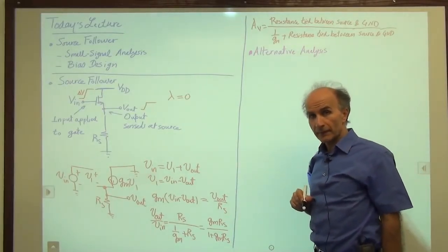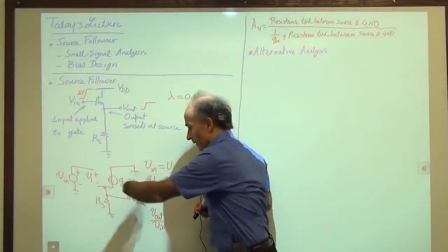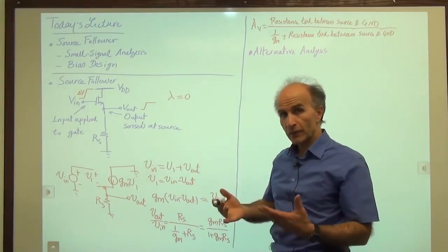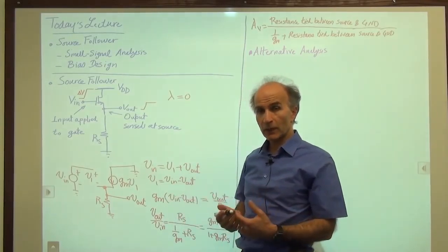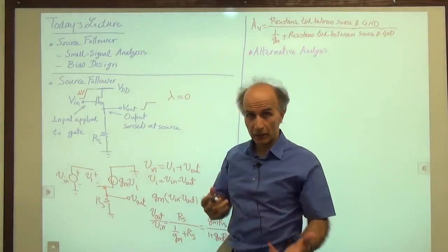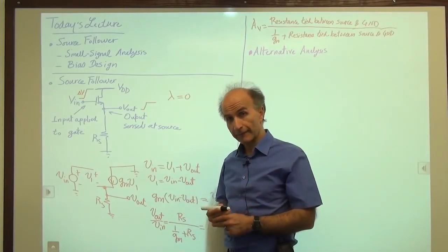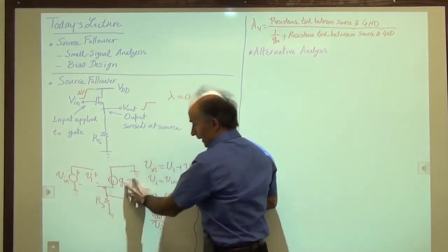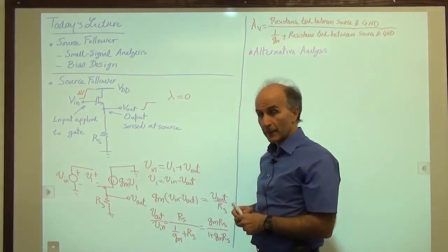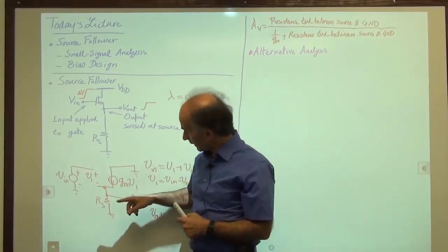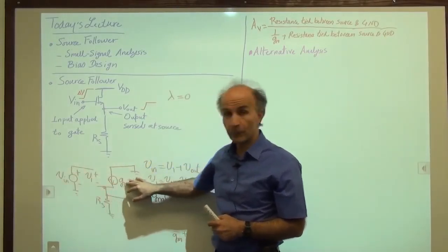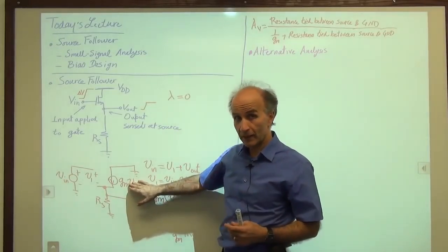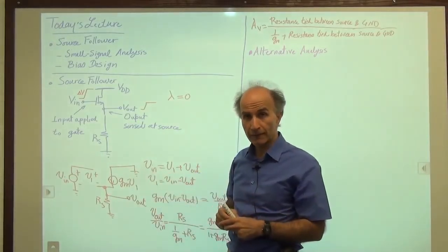All right, so let's do this. Rather than go through the small signal analysis and write all these equations, maybe we can use some of our knowledge from Circuits 101, namely Thevenin equivalent, Norton equivalent, that sort of thing, right? So maybe what I can do is this. I have the circuit, and I'm too lazy to write these equations. So I'm thinking maybe I can represent part of the circuit by a Thevenin equivalent, which hopefully is easier to analyze, and then connect everything together.